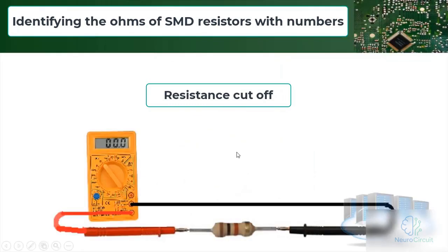The second type of failure that can happen to resistors is what we call an open circuit, or being cut off, so to speak. This means that you take your multimeter, connect it to both ends of the resistor, and want to test the resistor. What's the result? You see that the multimeter doesn't show any value. It's like those fusible resistors where when you connected the multimeter, it didn't show any value and, well, it was open. This can also happen to a regular resistor with a certain resistance value, not just fusible ones.